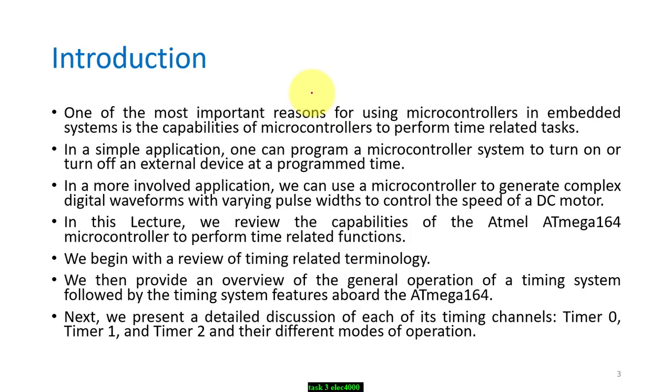Now, usually when you want to create an output signal, we are going to use a delay signal. Delay is not good for programming because when you put a delay signal, this means the microcontroller has nothing to do in that time. So you delay the whole work of the microcontroller. So it's not a good way to program using delays. Instead, we are going to use timers and counters.